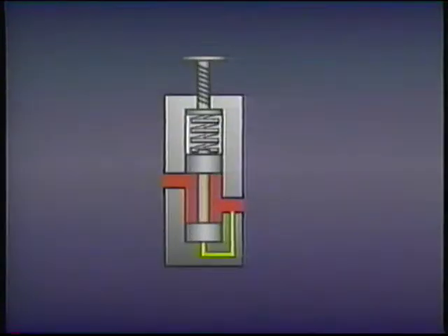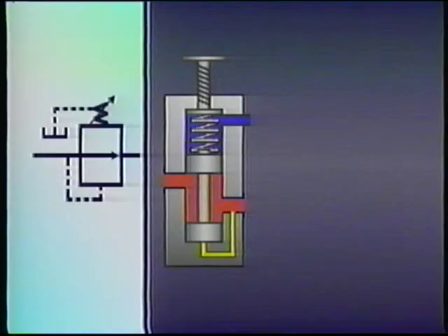However, the secondary ports on pressure-reducing valves and sequence valves contain fluid at working pressure. Trying to drain the spring chamber into the secondary port in this case would prevent the spool from shifting properly. In these situations, the spring chamber must be drained through a separate or external line. External drains are indicated on the symbol with a dotted line from the spring area to a tank symbol. Internal drains are not schematically illustrated. If the symbol does not include this dotted line to tank, the valve is internally drained.